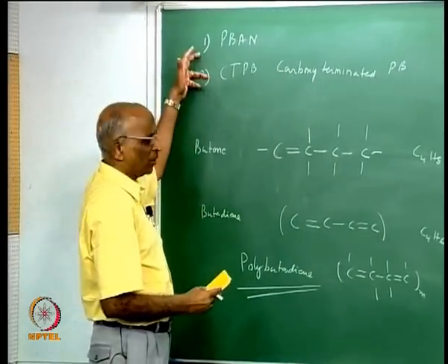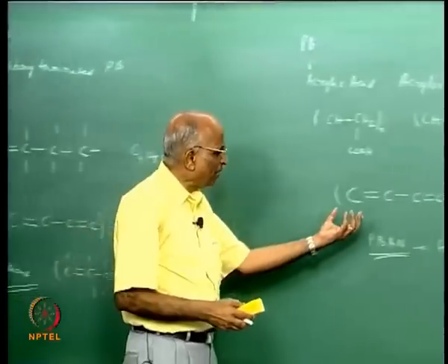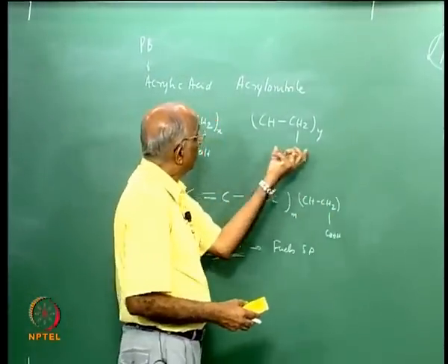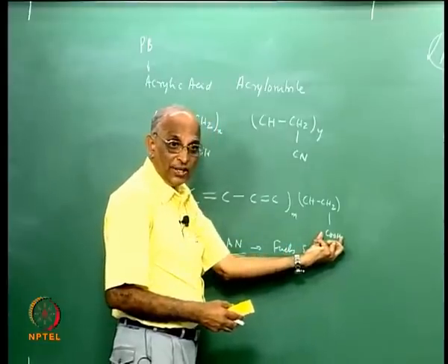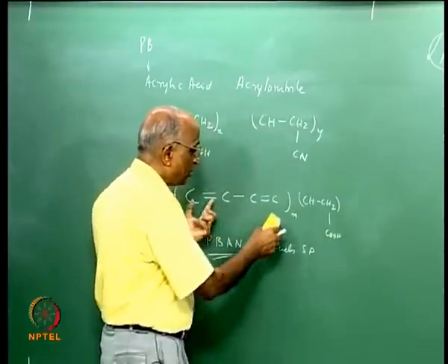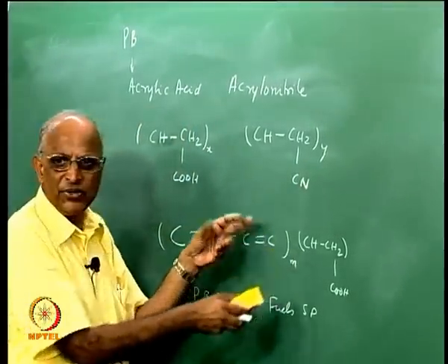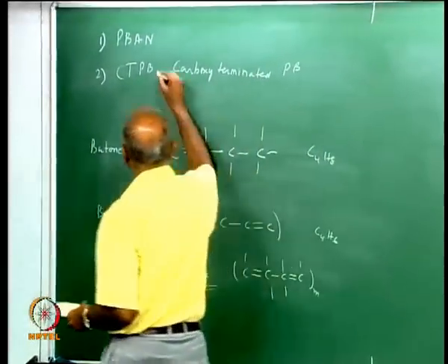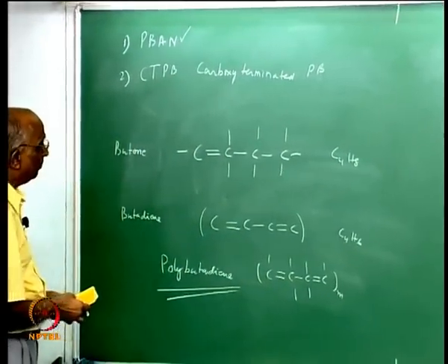That is the second fuel. There are not many, just some 2-3 of them. All what we have done is we remove the acrylonitrile part of it, keep the carboxyl acid here, and we stop the chain here. Maybe it gives little better properties and little more energy than a PBAN propellant. But the choice for major booster today is still PBAN. We see whether some improvements are possible.